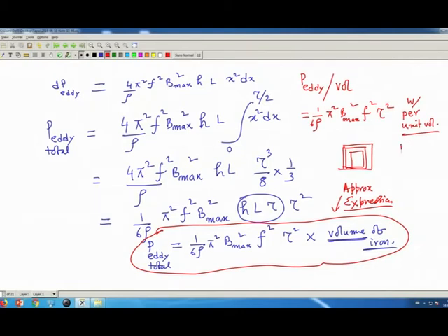Instead of that, you use plates, and the eddy currents will be confined only here, because the next plate is insulated from the other. If you do not use insulated plates, then the story remains the same, the eddy paths will be more. That is why the insulation is necessary.